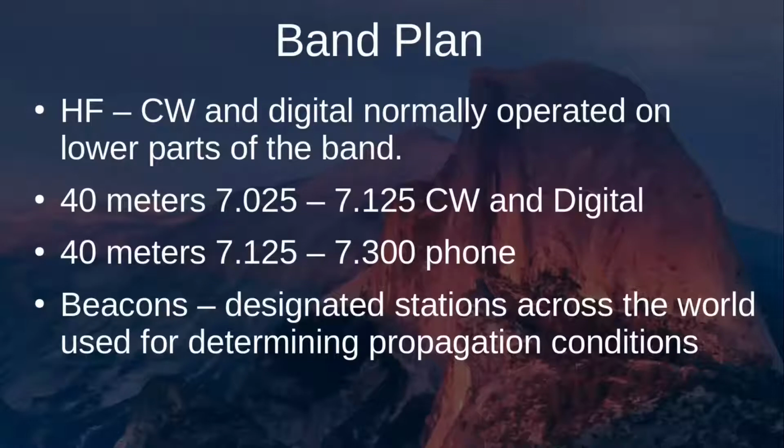And beacons also exist. Beacons exist on certain frequencies and they're designated stations across the world, and they're utilized to determine propagation conditions. So let's say there's a beacon station in London and maybe another one in South America and another one in Africa. These beacons have designated frequencies within the FCC determined allocations, but they're agreed to be within a certain band plan or frequency so that amateurs can find the frequency and see if the band's open.